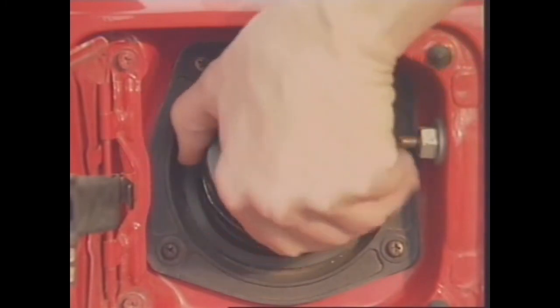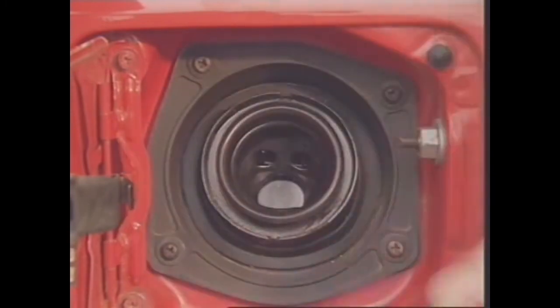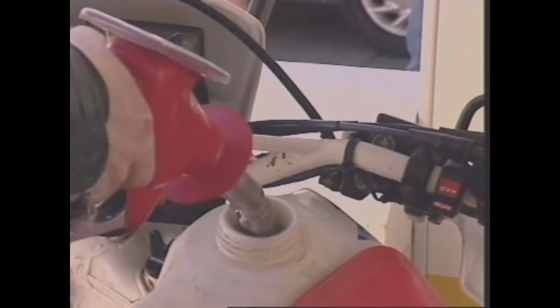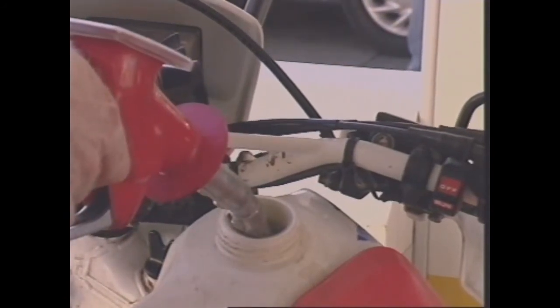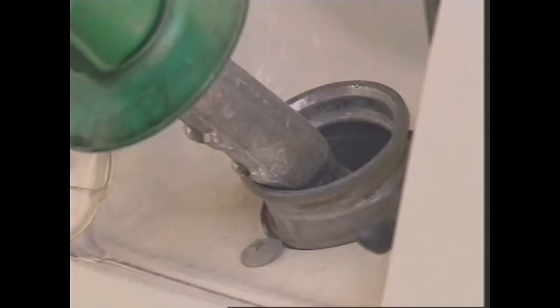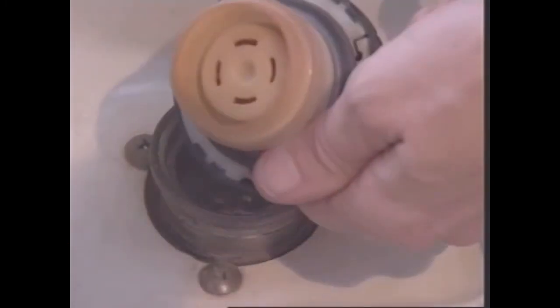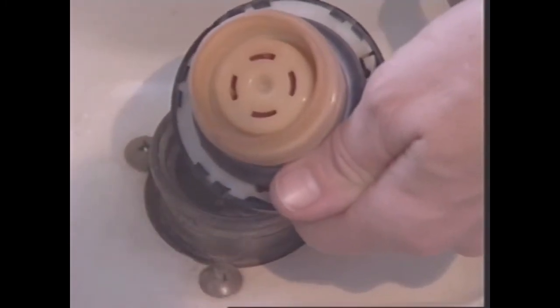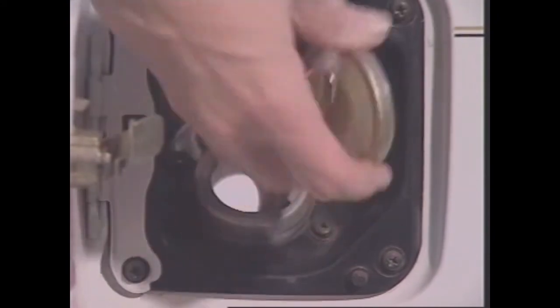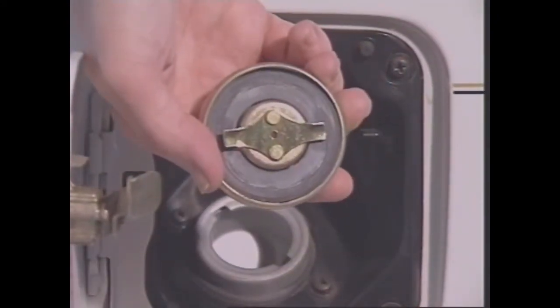Water can corrode internal passages of fuel pumps and carburetors. The cap on the petrol tank also stops petrol vapour escaping and polluting the atmosphere. This is important for petrol, which is very volatile and vaporizes easily, especially in warmer climates. Some petrol caps have a low pressure valve built in. It keeps a balance between the pressure in the tank and the outside atmospheric pressure.